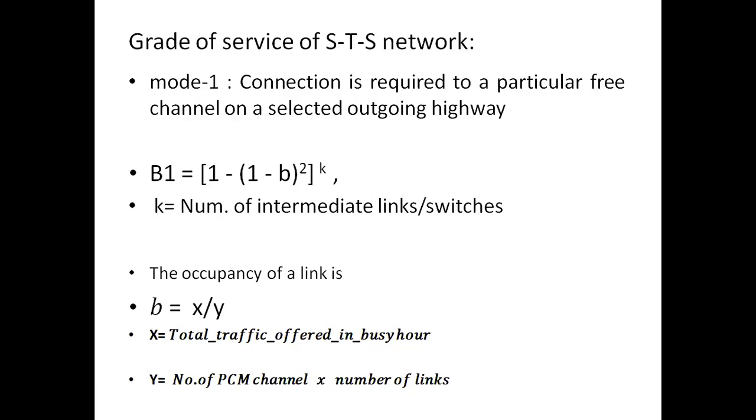It's not like you select some random free outgoing highway to switch the incoming PCM channel. In this case, the connection is required to a particular free channel on a selected outgoing highway. You have already selected a particular slot to which you want to transfer or switch the incoming PCM channel. The grade of service of such a mode for the STS network is given by B1 equals (1 minus b) whole squared, this whole term to the power of k, where B1 is the representation of the grade of service of the STS network.